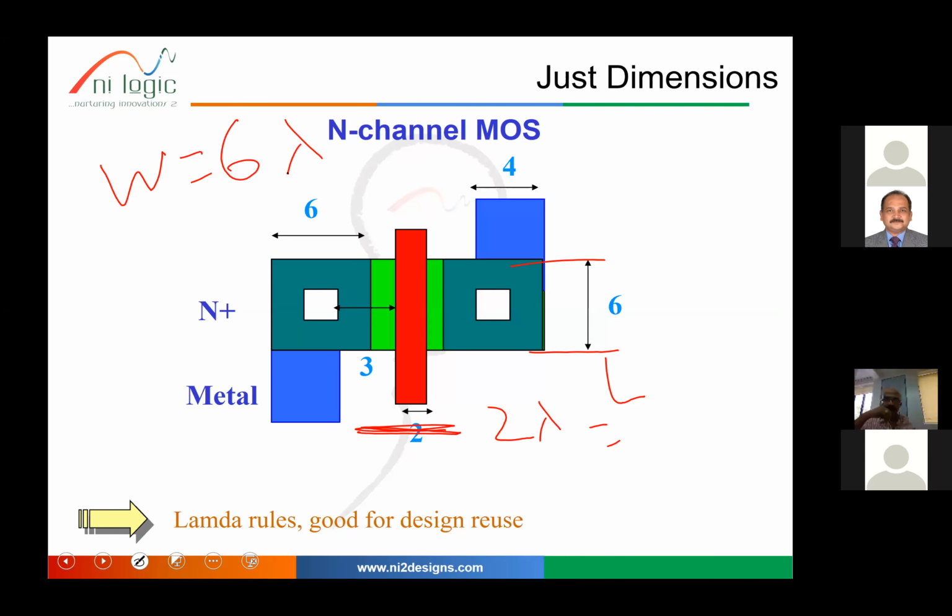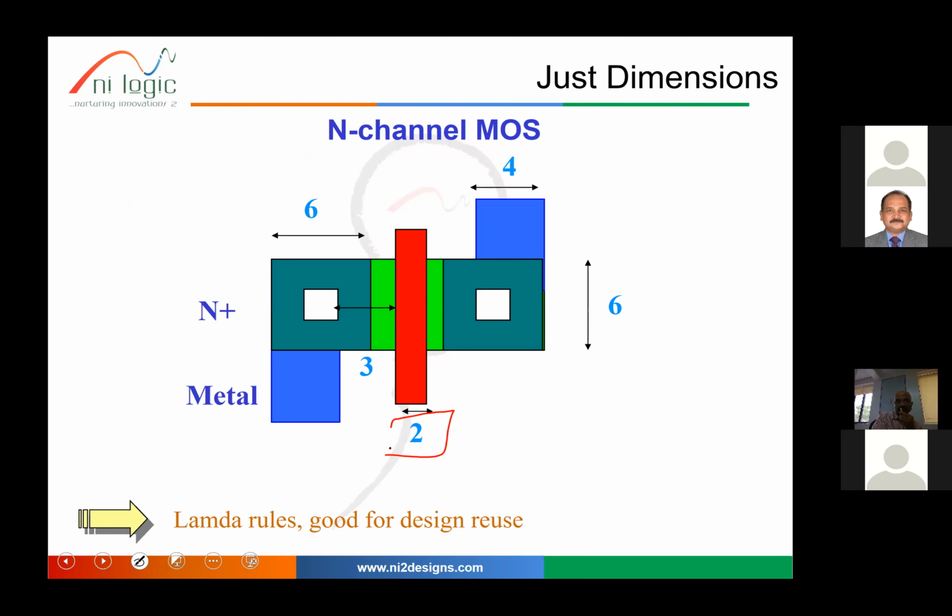Can I get some answers? Just to know the opinion of the common thinkers. I believe everyone has got the question. I have mentioned that yes, we can design a transistor and MOSFET, and these are the minimum values: length should be minimum 2 lambda, and the width should be at least 6 lambda.